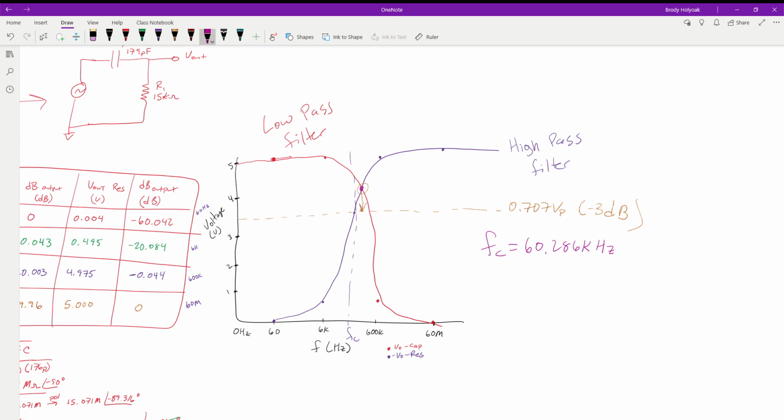So kind of going back to the audio, I'm going to use the radio that we have set up in the back of the class again as an example. The different colored lights that it has on it are actually wired up to filters. What happens is, with the audio signals coming in, they filtered out the bass signals, they filtered out the mids, and they filtered out the highs. So anything that was lower than a certain frequency, they would strip everything else down and then send just that data to another set of amplifiers to boost up the signal again.